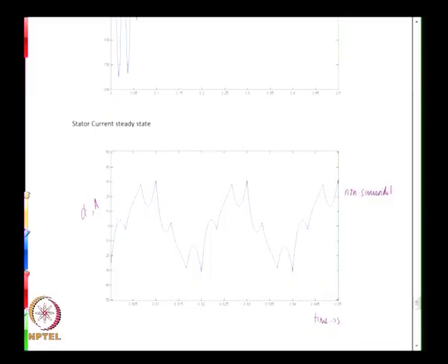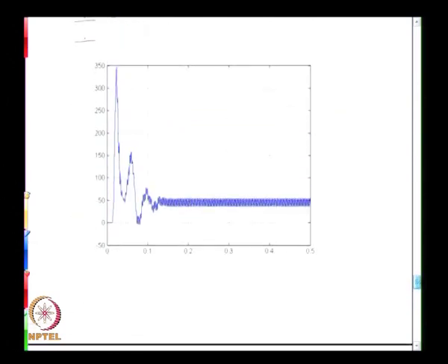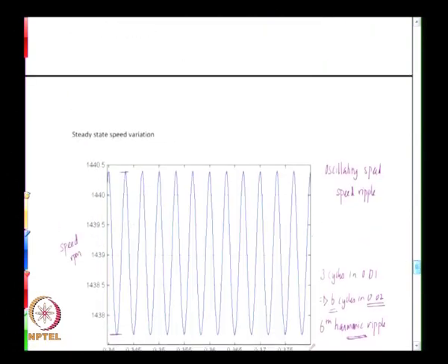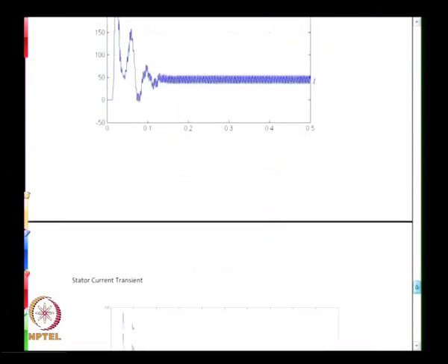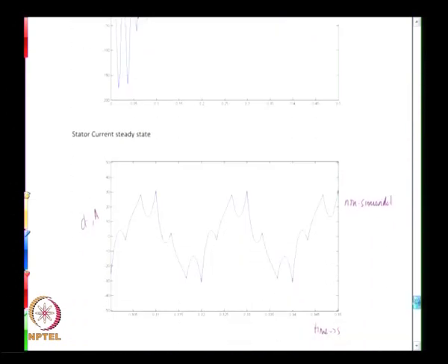These harmonics also result in oscillations in the generated torque TE and therefore in the speed waveform as well. But if you supply an induction machine through an inverter that is not specially controlled in any particular way, with simple square wave operation, you just can't avoid significant harmonics at low frequencies, and that results in this kind of distorted stator current waveform.